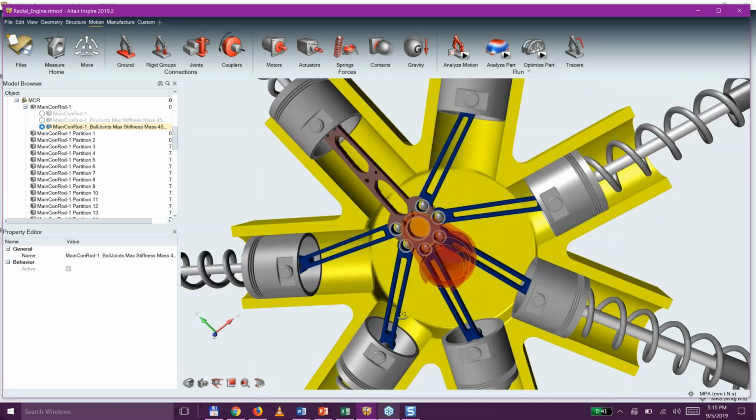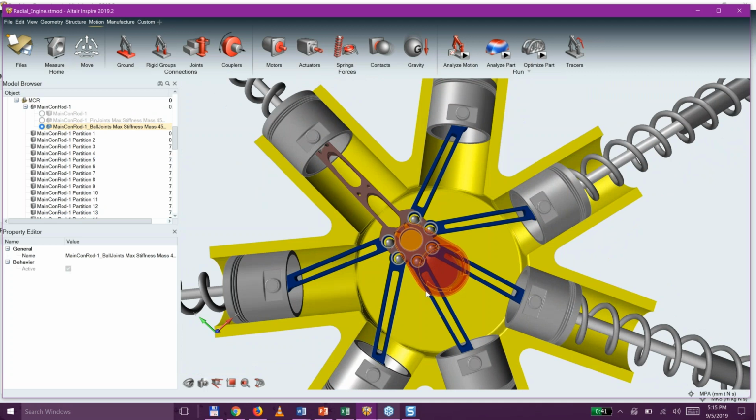And then they got those 2 shapes there. So that's how we can drive an optimization using the motion. It's no different than running an optimization normally in Inspire, except for the fact that as opposed to putting forces in, we put the motion values in there, and it will calculate the forces for you.